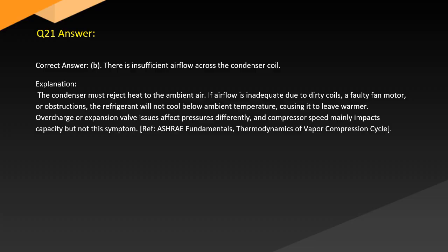Overcharge or expansion valve issues affect pressures differently, and compressor speed mainly impacts capacity but not this symptom. Ref. ASHRAE Fundamentals. Thermodynamics of Vapor Compression Cycle.